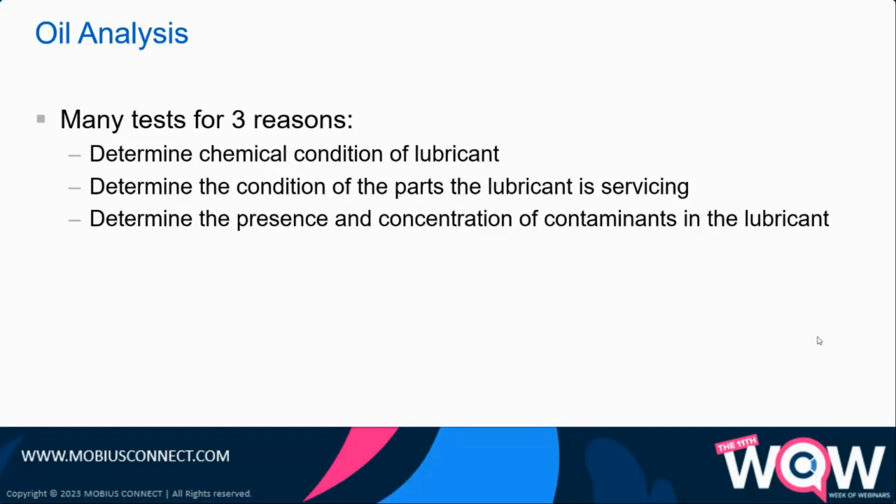It's also a complementary technology to vibration. If you have elevated vibration in an asset, say a gearbox that has a lubricant, you can look at oil analysis trends as well, and they go hand in hand to help understand what the actual failure mode is that's occurring in what component, right? So it helps in that investigative process before corrective action takes place.